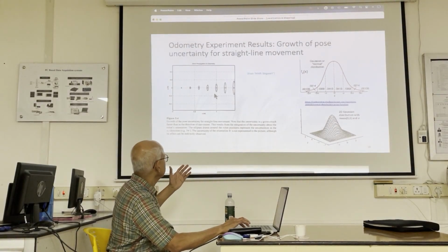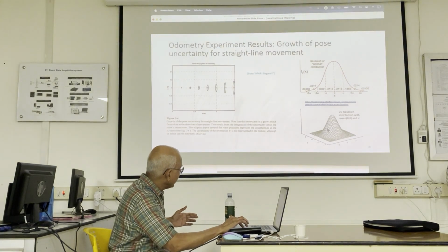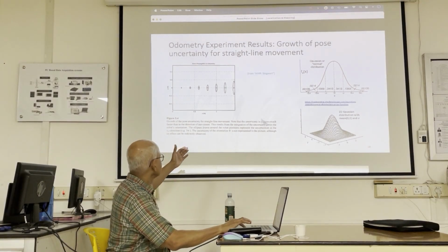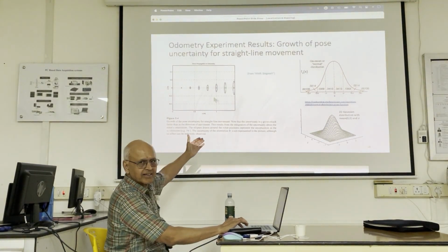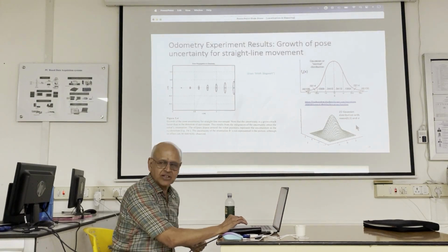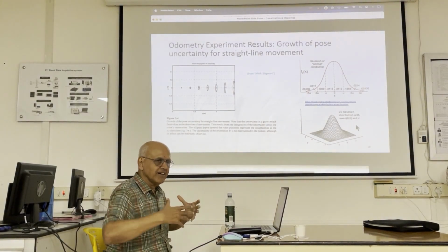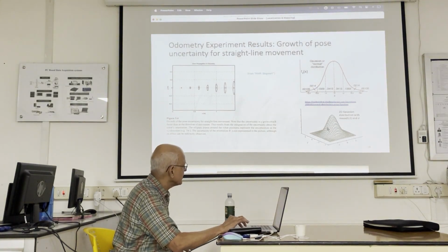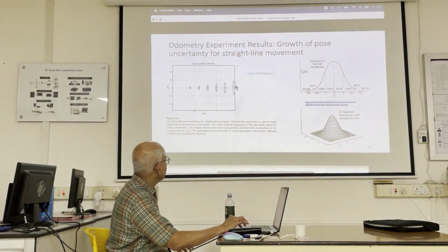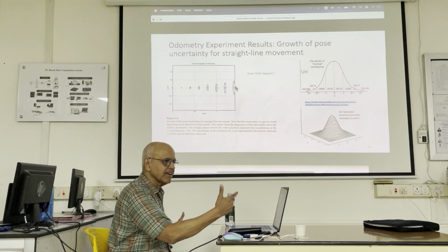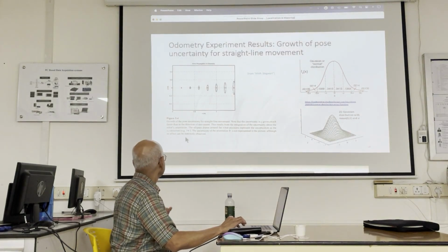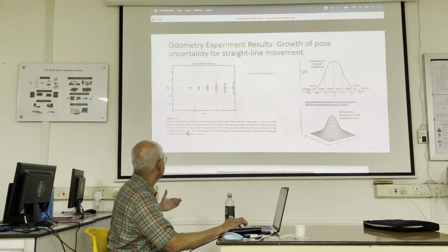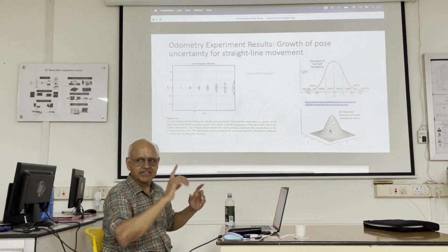So by the way, you're wondering where did this come from? You can take this Gaussian, and if you section it, you get an ellipse, right? And what we are plotting is a section, because how can they show the Gaussian there? So what they're doing is they're showing a section of the Gaussian in order to convey whether it's uncertain, more uncertain, or less uncertain. So essentially, they're taking a section of the two-dimensional Gaussian and showing it here. I think this may be like 3 sigma or something. Oh, somewhere here they say, yeah, 3 sigma. Here it is. The ellipse drawn around the robot position represent the uncertainties in the xy direction, 3 sigma. So 3 sigma, they're cutting it.